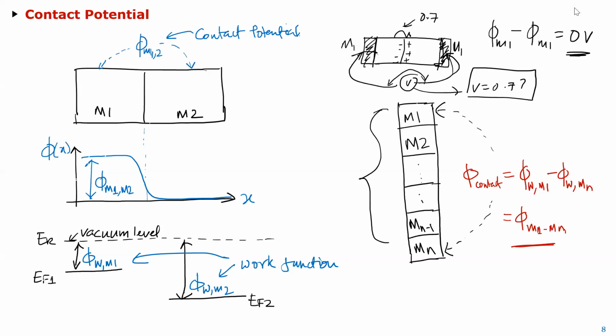Yeah, in the design, when we have this poly, then the contact, then the metal, then the via, all that stack is there. So there is a potential drop, and that potential drop is because of the resistance, whatever resistance we have. But this potential is also supposed to play a role in that voltage drop, am I right? Correct. For example, if you take a diode and you forward bias it, this potential plays a role, because that forward bias is not going to give you a current right away, right? You have to fight that potential for some time.